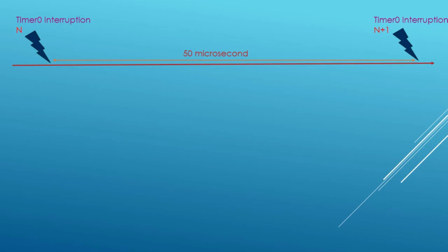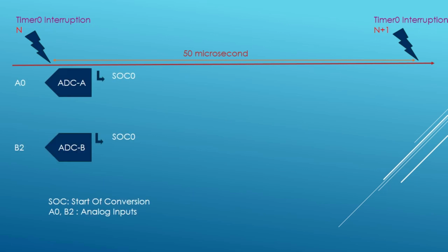This tutorial uses a timer zero interrupt. This interrupt service routine is an infinite loop of 15 microseconds. For this tutorial, I'm using ADCA and ADCB to demonstrate the conversion and adjustment of a measured input and subtract an offset of 200 points. I'm using the timer zero code tutorial. A card will show up in the top right of the video screen.